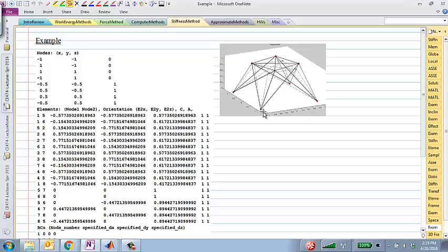In this example, I have this three-dimensional truss. Looks complicated, but on the base, I have these 4 nodes. Okay, so let me point them out. I have these 4 nodes on the base, and I have 4 nodes on the top, and I have lots of connectivity between all of these elements. So I will definitely have more elements than equations. So this is a highly indeterminate truss.